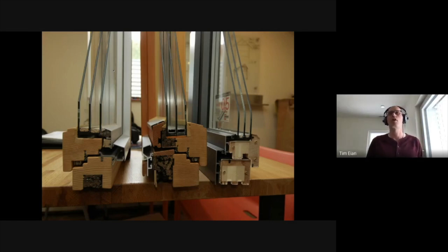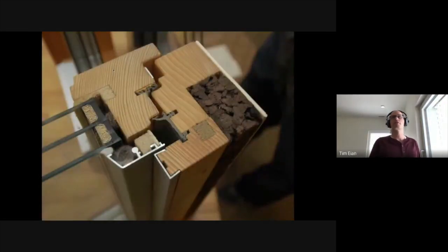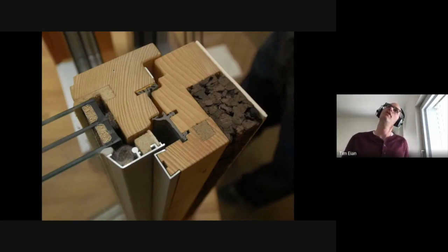They're made up of argon-filled triple pane glazing units with what is considered a Swiss spacer, or a very low conductivity spacer around the edge of the glazing, and then generally a thermally broken frame of sorts. You can see these are some beautiful examples using hemp and cork as insulation materials. And then on the right-hand side, there's one that uses a composite and foam. Again, just like in any building, we have choices in the marketplace. These are just a couple. Here's another cross-section of a window. This is actually the same window that I'm standing next to here in my building.